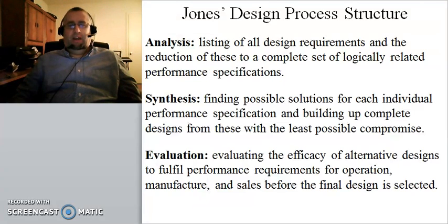So using the quantitative metrics that you established based on customer needs and design constraints in the analysis step to down select from among all of the possible solutions that you came up with in the synthesis step to what is effectively the best solution to meet that particular design challenge. So that's the evaluation step.